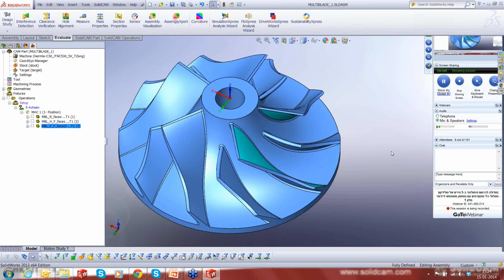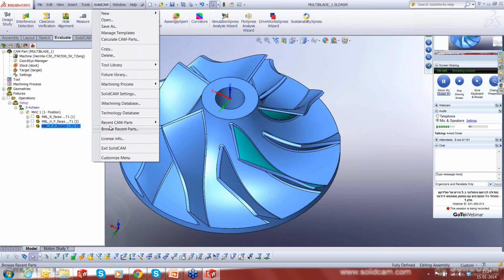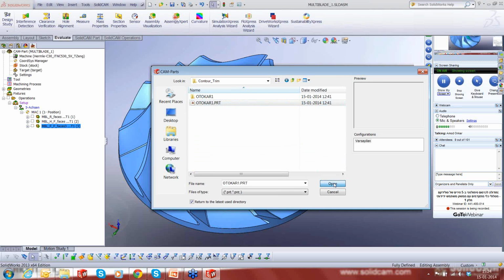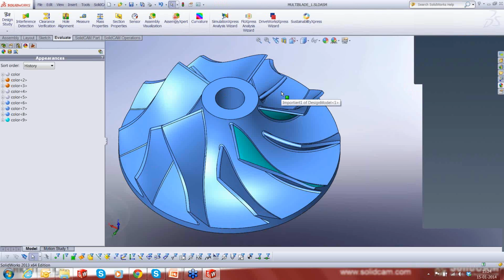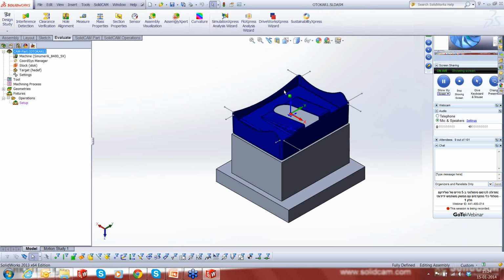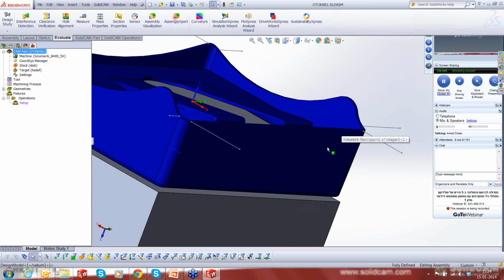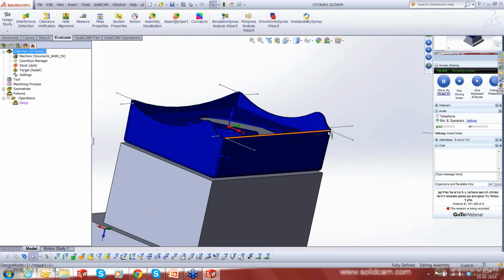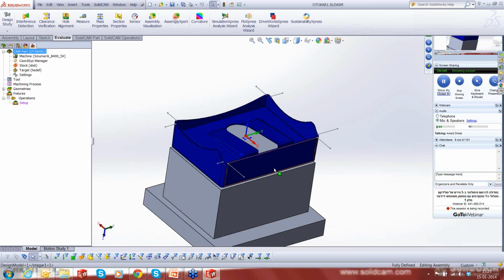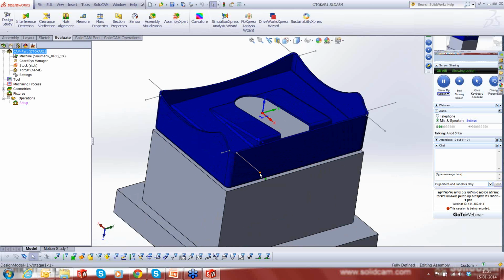Right, so we have seen swerving and we have seen this new application for multi-blade machining. Let's move to another area, and that's trimming of vacuum form parts. So let me open a part. Okay. So we have got this part out here whose edges need to be trimmed out because it's a vacuum form part, and I want to trim it exactly to this edge, because in vacuum forming you really don't end up getting this edge. So we need to form that.